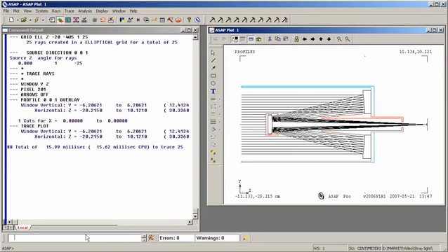We're then going to circle back. We're going to model the scatter properties in a more realistic way, showing how the BSDF fitting utility in ASAP can be used to model not just simple BRDFs like Lambertian BRDFs, but can also be used to model very realistic BRDFs, and this can be done in a relatively straightforward way, even by beginning users. We're then going to show how ASAP's importance sampling or directed scatter capabilities allow us to get the calculation done very quickly.